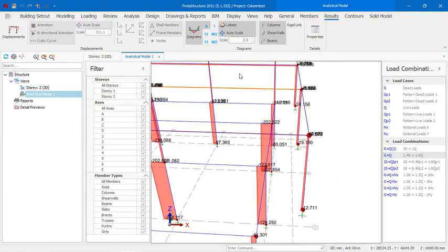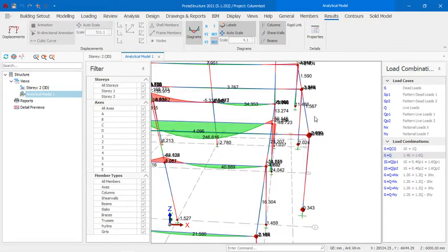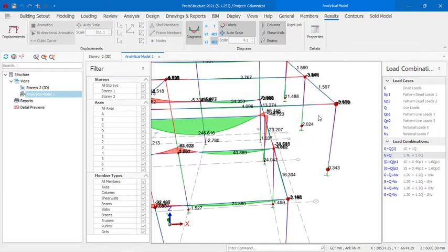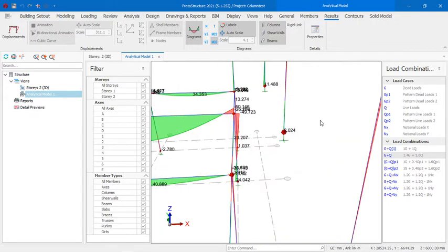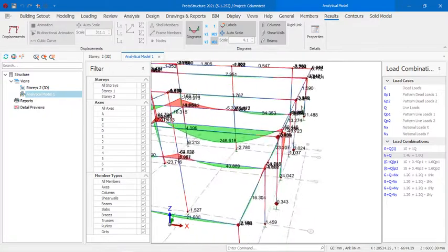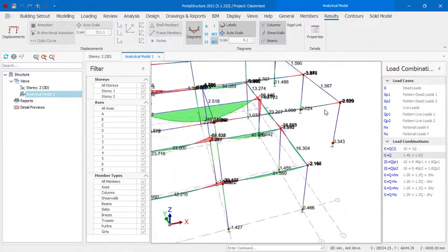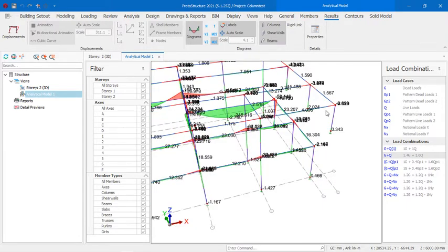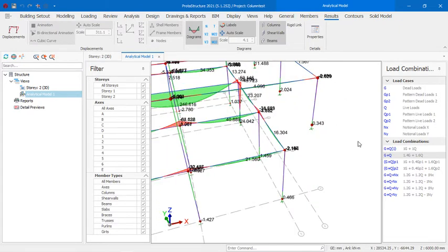So in this case, you can now see that there's lesser movement in our beams, because it's no more dangling, because it's now resting on a support, which is the case, which is what I've idealized. So I have idealized and I have modeled my design intention in the software, and I'm getting a result for it, which is okay. So by that I'm confident.